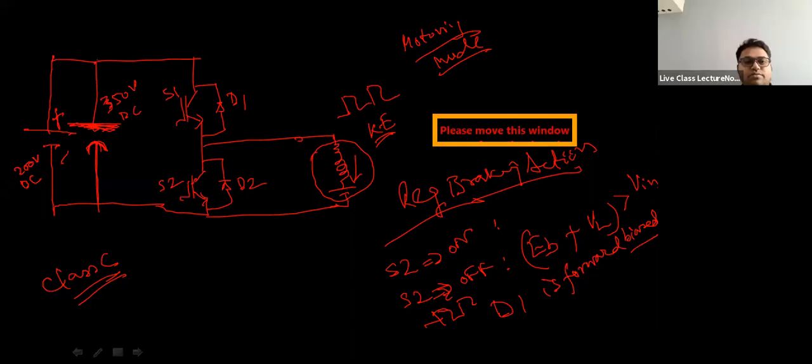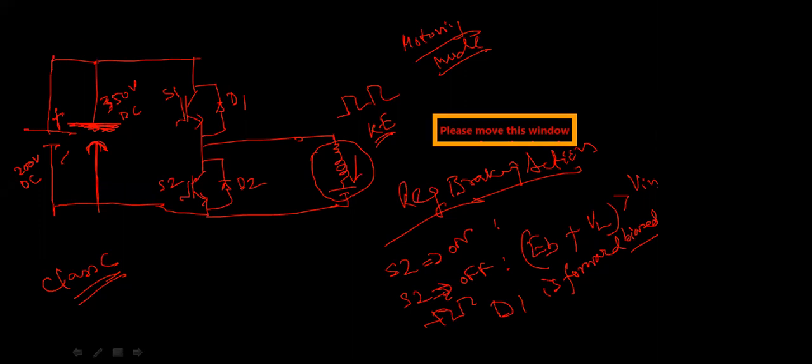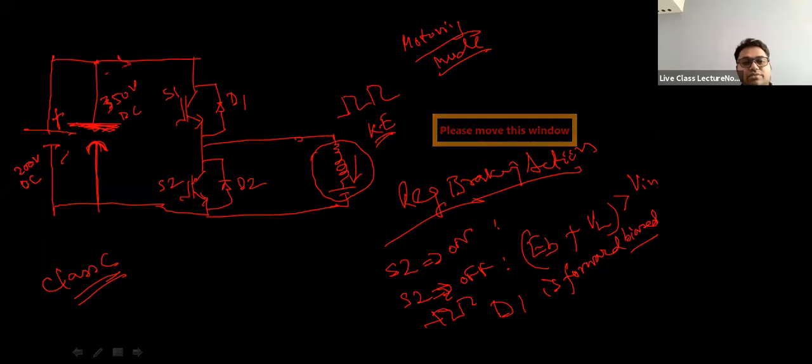See, first of all, so what will happen? The capacitor will discharge first, right? So it will keep on discharging till both the voltages are the same. So this will be 200 volts also, and this will be 200 volts also. So first, the energy that was stored in the capacitor is now reused for motoring. So do you get it?